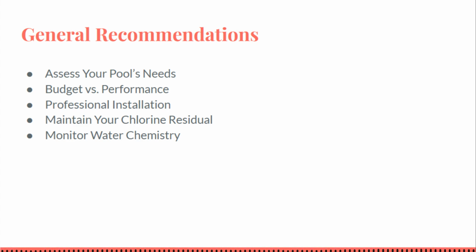Professional installation. Consider having the system installed by a pool professional or follow manufacturer instructions closely if DIY. Proper placement in the plumbing, correct injector sizing, and integration with the pump automation are key to performance. Ensure any needed accessories, check valves, flow switches, degas vessel for AOP if recommended, are included.